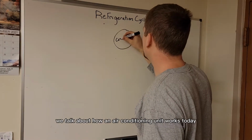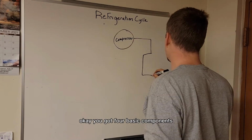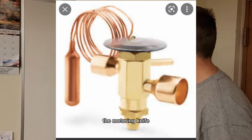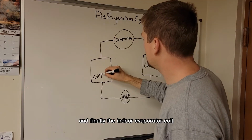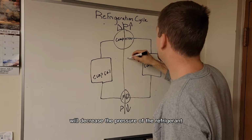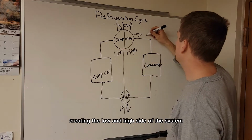Thought we'd talk about how an air conditioning unit works today. Okay, you've got four basic components of any air conditioning system. You've got the compressor, the condenser, the metering device, and finally the indoor evaporator coil. The compressor will compress the refrigerant, increasing its pressure. The metering device will decrease the pressure of the refrigerant, creating the low and high side of the system.